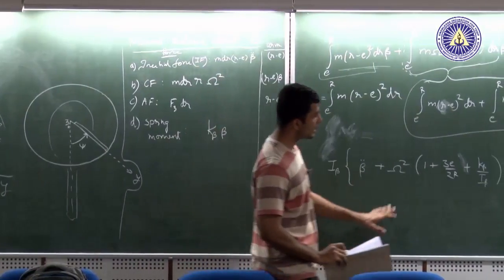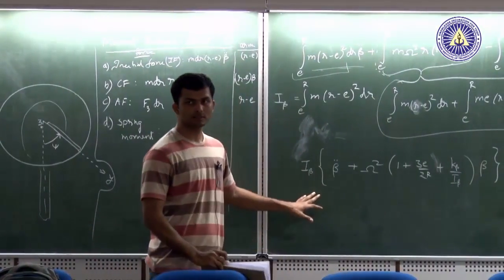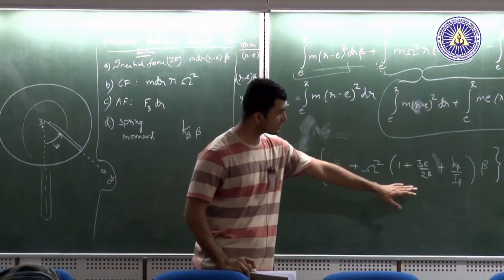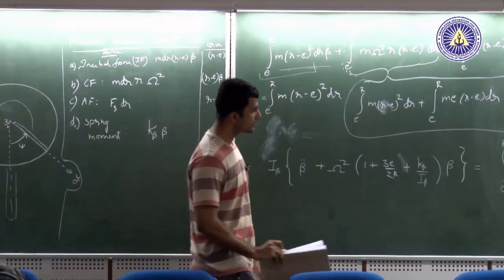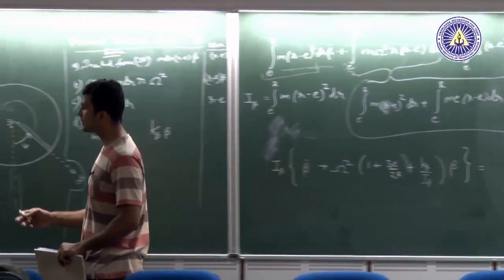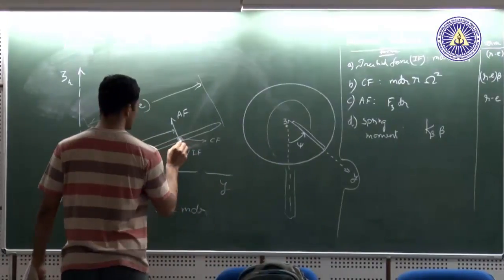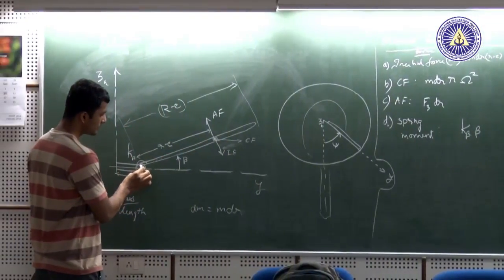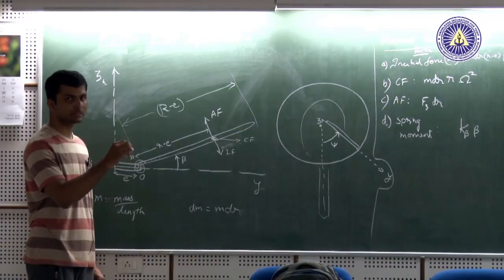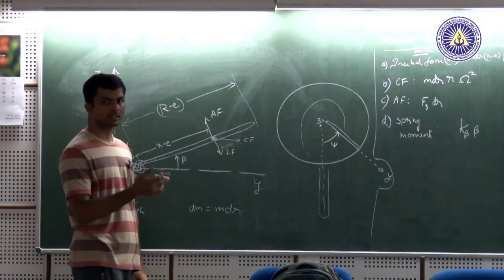Okay. And where is the control input appearing? Because there is no control input on the left hand side, but you have this F_z term, which is this aerodynamic force at that elemental location, integrated from here to here, and that is where the control input is hiding, and it has not yet come out.